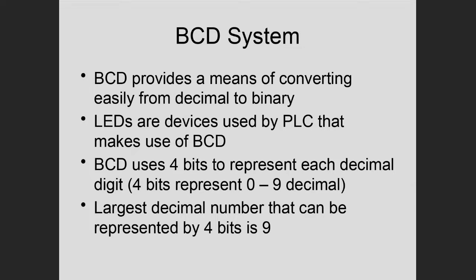Well, basically you're going to use BCD anytime you have a digital device that requires a number input or output, like, say, a digital readout. You want something to read the numbers 0 through 9 or some combination of digits. Or you have something called a thumb wheel, maybe like an electronic lock, where you can dial numbers into a system. When you have numbers inputted or outputted that way, typically we don't use a weighted number system. We use BCD, binary coded decimal.